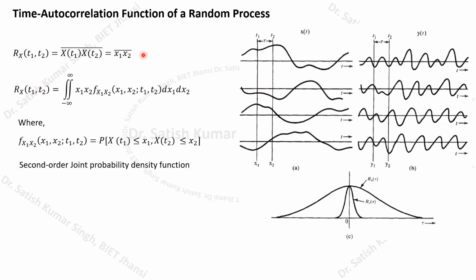Remember that any random process, specifically a noise process, is considered a power signal, not an energy signal, because the noise is available for all time, varying from minus infinity to infinity, and therefore can contain infinite energy. So we calculate the autocorrelation function, and its Fourier transform gives the power spectral density function.